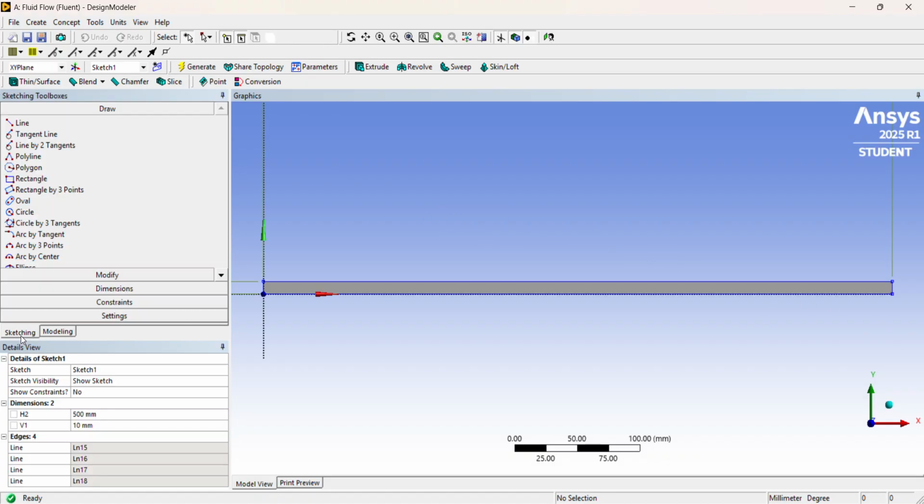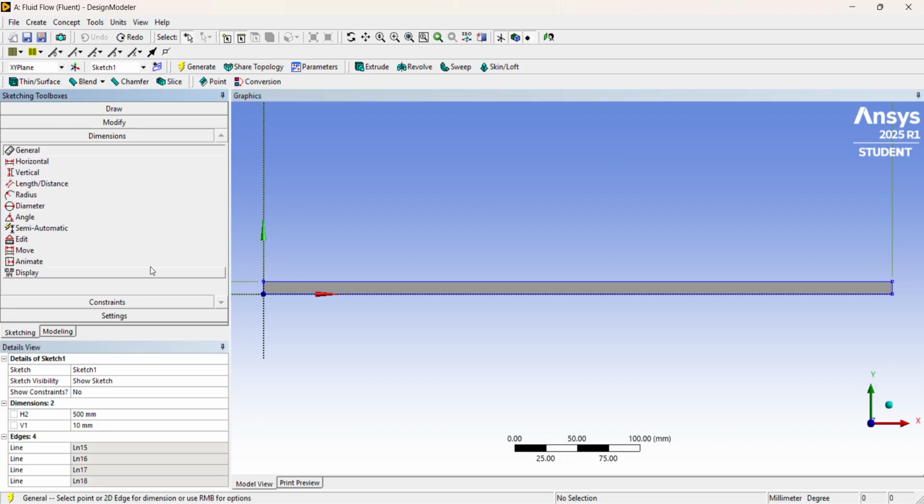And then what you have to do is go to sketching. You have to make your rectangle, and then you would start out, drag it, kind of like that, and then make that, and then your dimensions. I chose, as you can see down here, you would use these two tools. My dimensions, the length of it is 500 millimeters, and the height of my pipe would be 10 millimeters, just to make it so that everything is laminar for the Reynolds number, so that the number is 2000, so that the entire flow can be laminar.